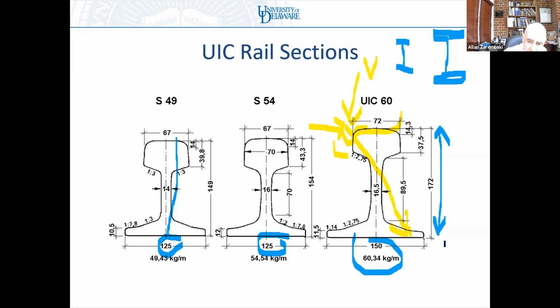And the reason is, if you remember your equations from engineering mechanics, the moment of inertia for a rectangle is BH cubed over 12. So the height has a cubic effect, whereas the base has a linear effect. So I get much more bang for my buck, so to speak, if I increase my height. If my goal is to increase my moment of inertia to reduce my stresses, I get a much more efficient use of material by increasing my height. Did I answer your question? Okay, thanks.